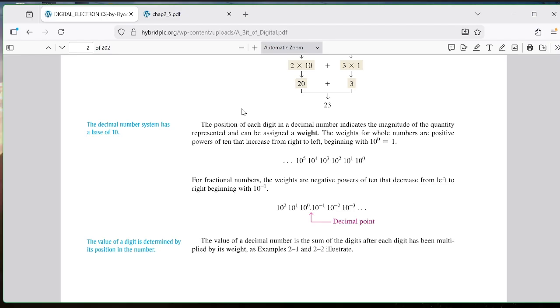And if you wonder where that's leading, in the PLC there are 3 basic languages. One is ladder, but then one is called FBD, function block diagram, and function block diagram is these gates. So when you're studying the gates, the and, the or, the nor, the gate logic, you're actually building those on the screen. So that's called FBD, function block diagram. And you can flip back and forth. You can be in ladder, then in FBD, and back in ladder, and just do that all over the place.